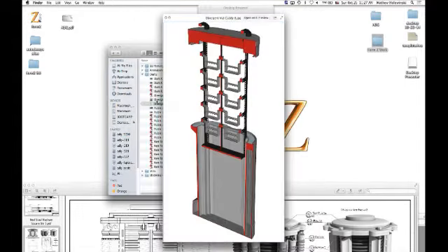So just using the section tools, you can cut through an object. In FormZ, the objects are all assigned attributes. So you can assign a line weight to an object and colors for where you cut through it. And you can do hatching patterns so that when you cut through objects, each object can have a separate hatching pattern. And as you pull the cutting plane, which is a live object, you can either see the whole object or section it at any portion, and it'll have all the hatching and line weight